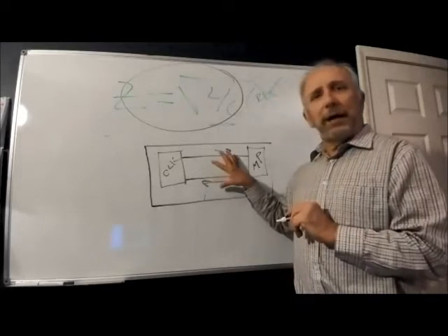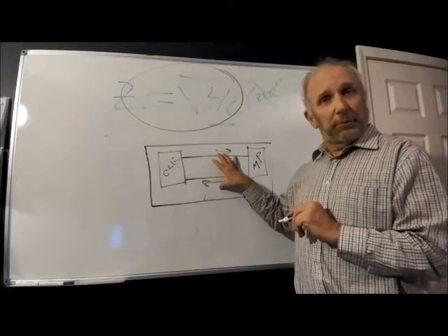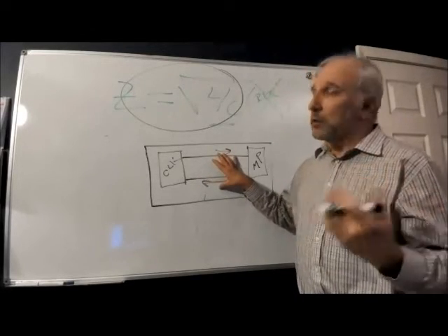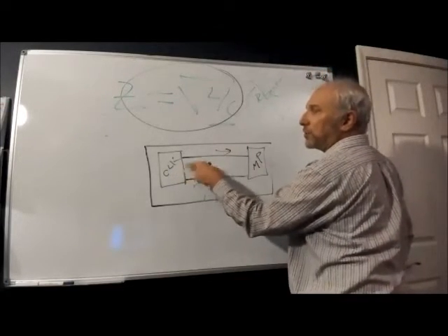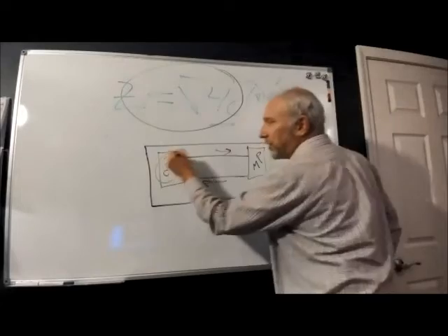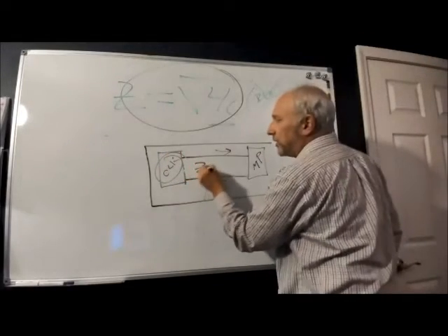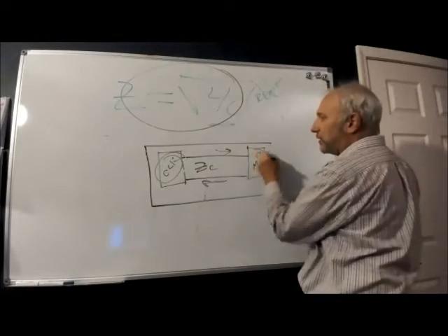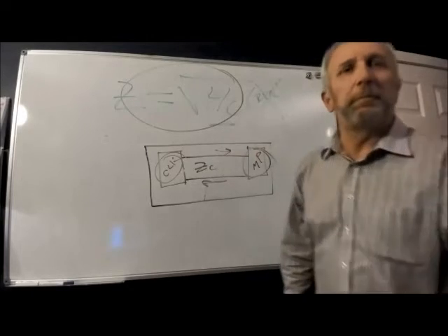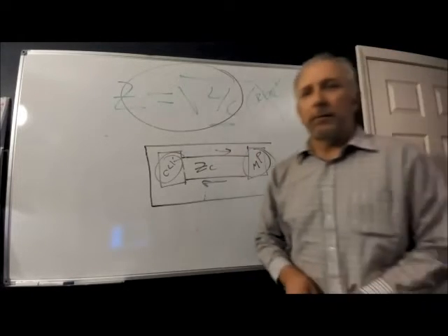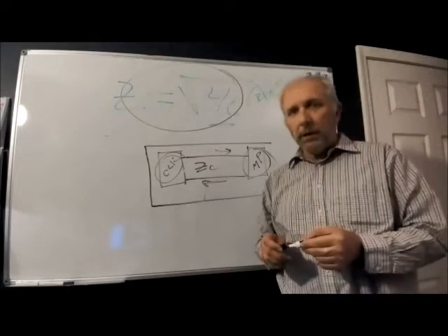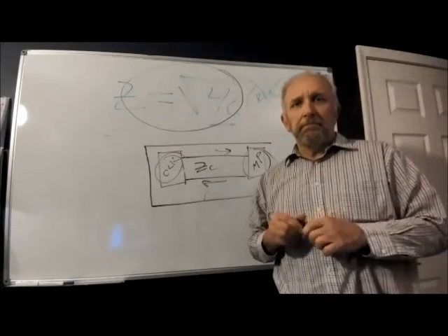If it turns out we have a transmission line on a printed circuit board, either intentional or unintentional, we probably want to make sure we get the correct impedance. So we want to match the impedance of our output circuitry to the impedance of our transmission line to the impedance of our load. So all this stuff really kind of plays together. Questions on that? All right.